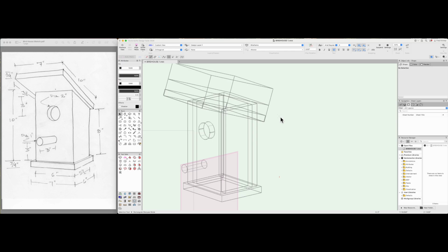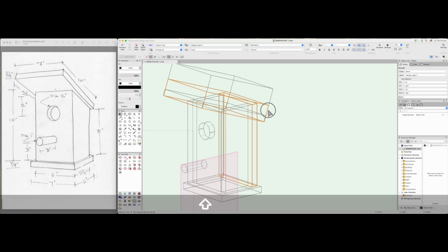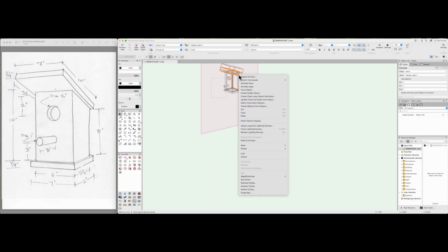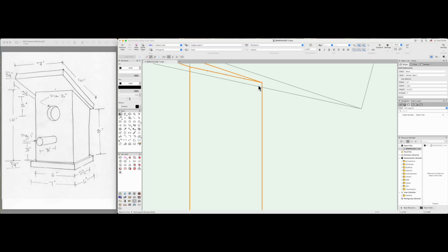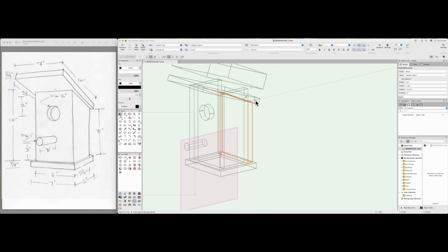The way that you would do it is you select the back, and then you select part of this deleting tool right there. By right click, what comes up is subtract solids. You want to hit subtract solids, and the one that's a redder orange is going to stay. The one that's going to be your tool to subtract will stay the original orange. If it looks correct, like it does here, you just hit OK. Now you can see this is now cut to fit this top part.